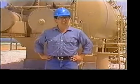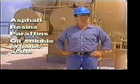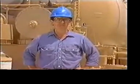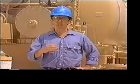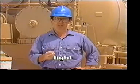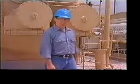The most common emulsifying agents found in oil field emulsions are asphalt, resins, paraffins, and oil-soluble organic acids. Different emulsifying agents will occur naturally in different reservoirs. In order to break an emulsion, these emulsifying agents have to be neutralized or destroyed. In the field, an emulsion may be called tight, which means hard to break, or loose, which means easy to break, depending on the type and amount of emulsifying agent present.